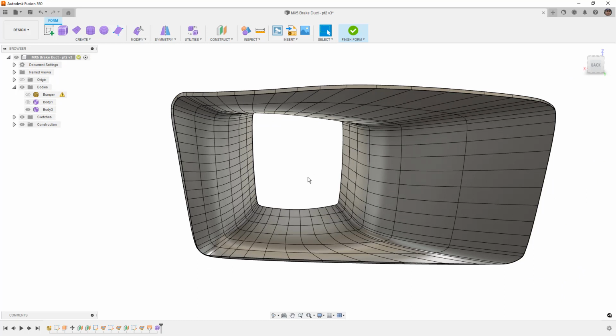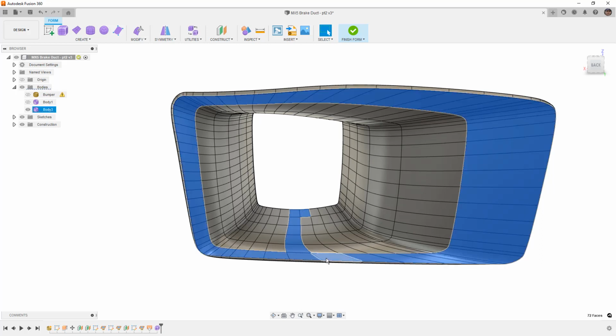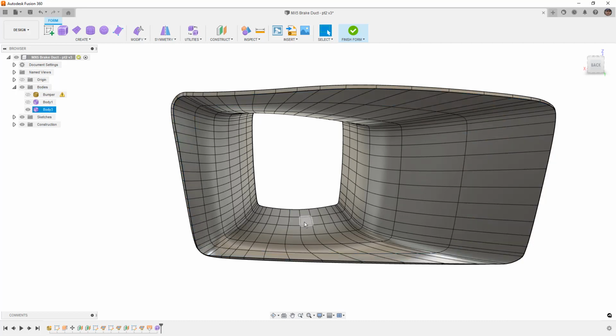So the next step for me is to divide this up. Now, if I want to divide it up all the way front to back, what I can do is take these sets of faces here, and then I can take the sets on the top and bridge them together. If I want it to be just partially divided, I could only take a handful of them. It just kind of depends on what your end goal is here. Remember that we're dealing with the inside and the outside of the form now. This is going to convert to a solid body. So we could get rid of and delete a bunch of faces, and we could patch the geometry back together to make a solid section over here, working with the inside and the outside consistently.